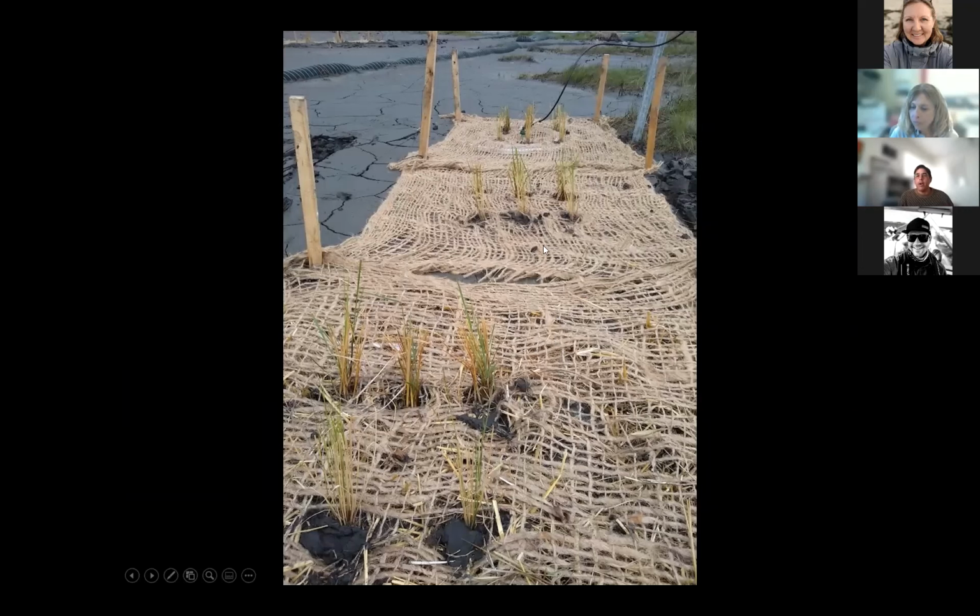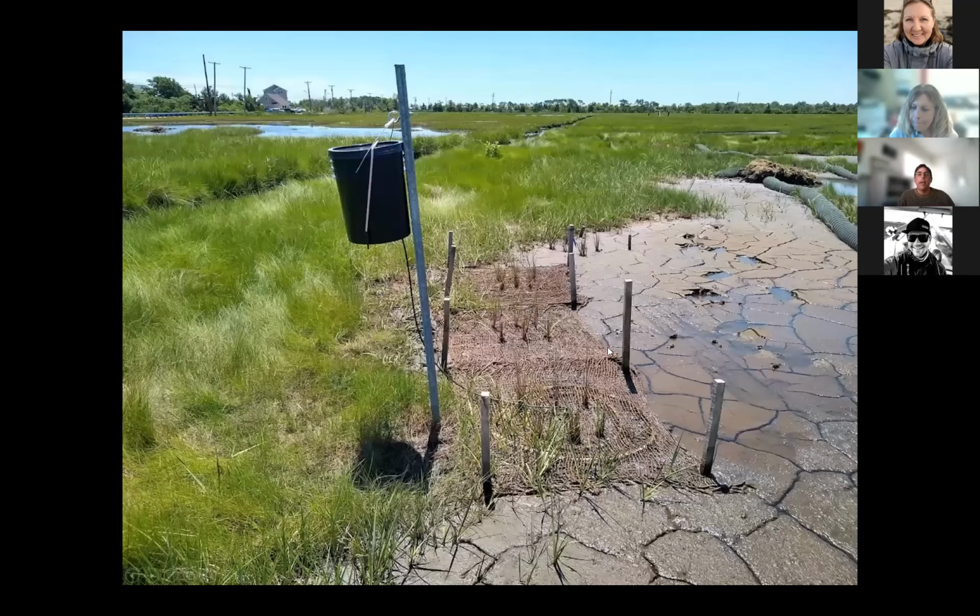One was this jute fabric covering. We also mixed some hay into the sediment with the jute fabric covering, with the idea of creating more connectivity between that lens of silt and the peaty material below, giving a moisture reservoir and a conduit for moisture to move up and down. That was the idea anyway. And then I went a step further and was playing around with drip irrigation, gravity drip irrigation.